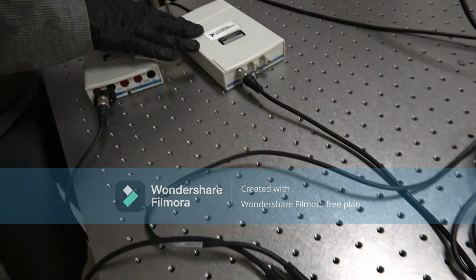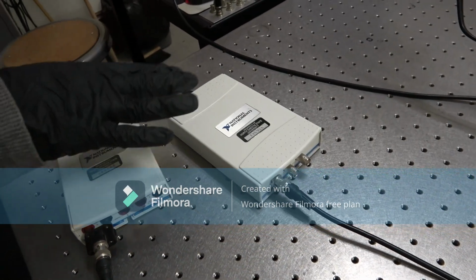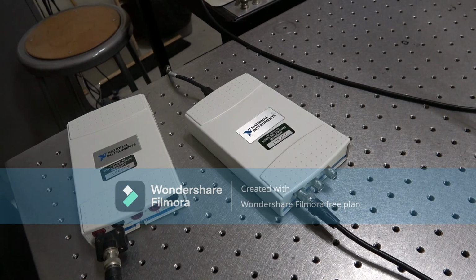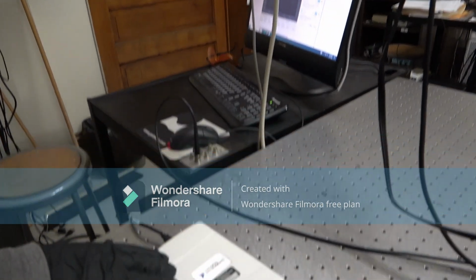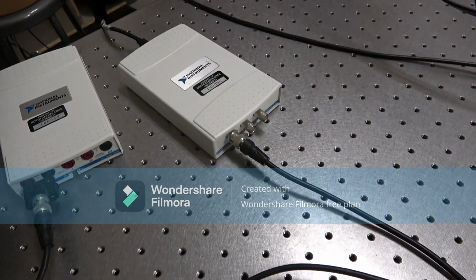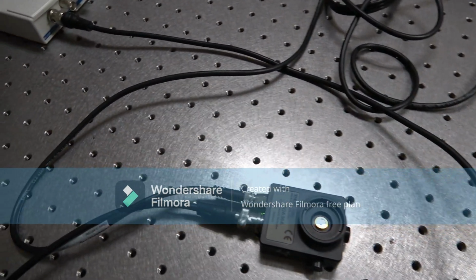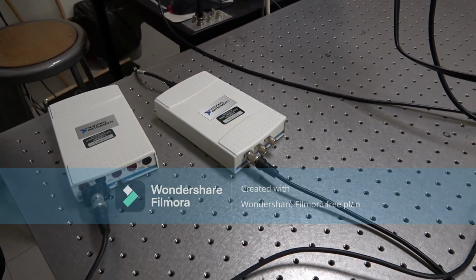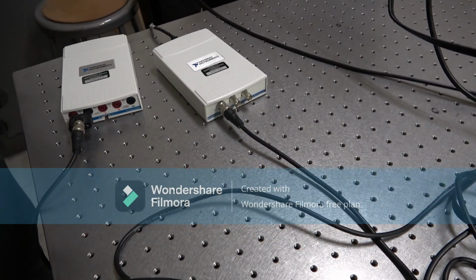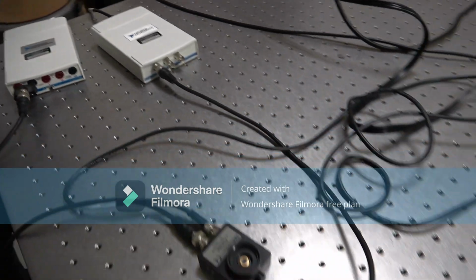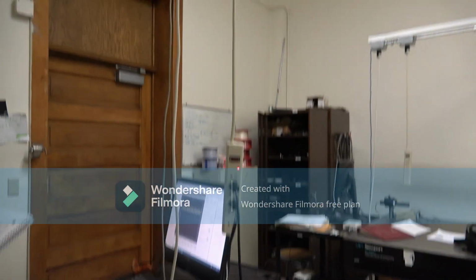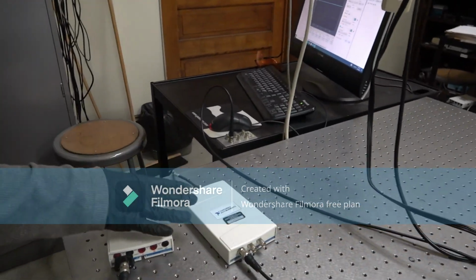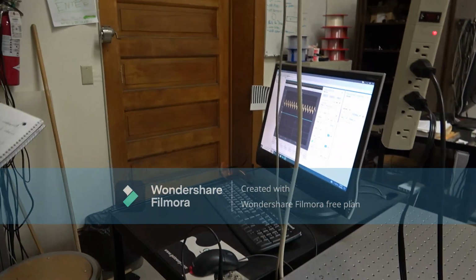And we have an oscilloscope. This is an electronic instrument that displays voltage waveforms and allows for various measurements on the software. And this is connected with a BNC cable, which is just an electronic cable that connects the device to the computer. The photodiode is positioned to face the ceiling light, capturing the ambient light, and this output is sent to the oscilloscope for further manipulation in the software.